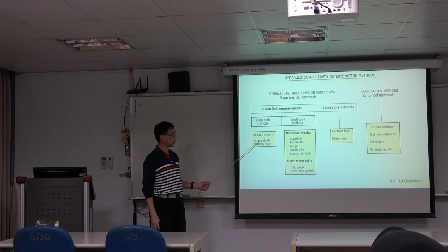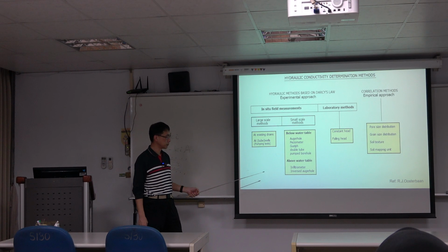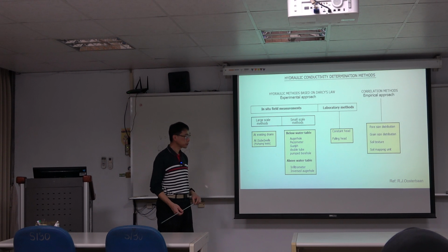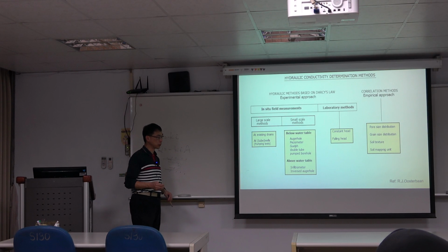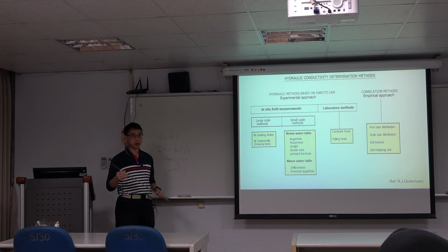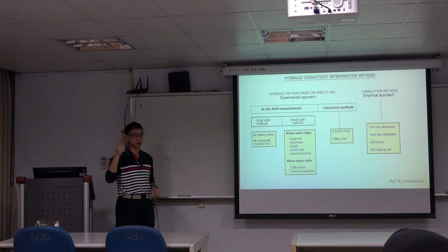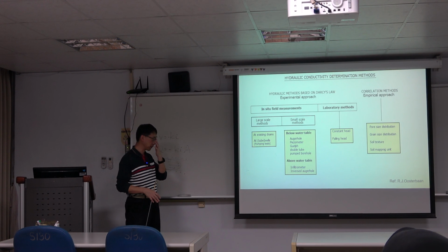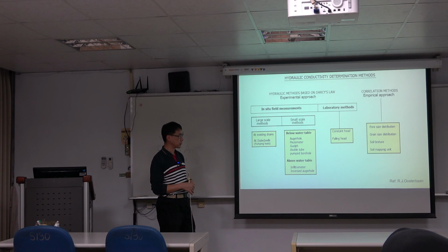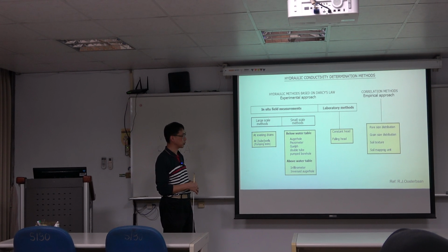And for in situ tests, we commonly have the pumping test and slug test. For the pumping test, we will go to our campus, where we have the well site. We can do the pumping test there, and I'll provide you the data set to invert and calculate the hydraulic conductivity and/or transmissivity. Try to do the operation for the pumping test. Okay, that's the important part.